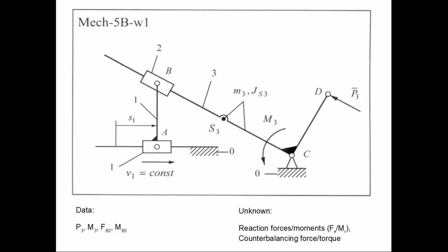What is this inertia force, or the moments of the forces of inertia? These are, let's say, fictional forces which are introduced in the mechanism to make use of the D'Alembert principle. I'll be talking about this in a moment, but first of all let's try to solve this mechanism using three different methods. What you want to know is the force which you need to impose on the driving link to make the mechanism move with the given velocities and accelerations which you assumed in the first part of the project.